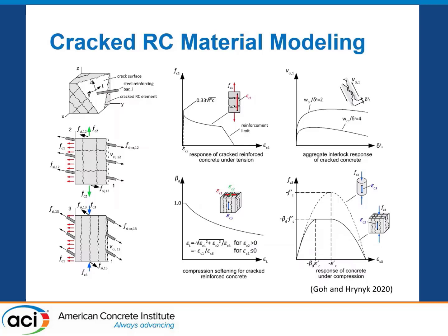And on the right side of this, it's just a very simplified overview of what this crack examination looks like. So imagine at a crack surface, on one side we have sound concrete and a set of stresses in concrete and reinforcement. And if you were to examine on the crack surface, you have an entirely different set of stresses because we're at a crack, but those things equilibrate each other. So this is all inherent to the model. From a user's perspective, all of this is going on behind the scenes.